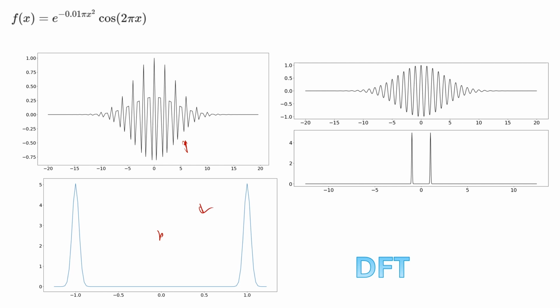When we lower the sampling rate, the bandwidth when we take the Fourier transform is 1 over 2 times the sampling rate. So if we lower the sampling rate, then the band that we cover is less. Down here, the bandwidth goes out to 10. Here, the bandwidth only goes from -1 to +1, and this 1 is approximately the extent of b, our bandwidth.